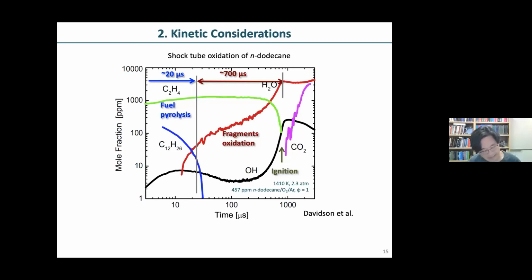So my point is, if you want to do NTC, might as well do it directly on the fuel. Some ideas we have is to take, for example, cetane number and octane number, and correlate these with the HyChem rate parameters. Then all you need to know is the octane number, the cetane number, and so on. Those should be directly related to HyChem parameters. This is the direction we're heading to. We're not done yet. That's all I have, but those are very good questions. Okay, thank you very much.